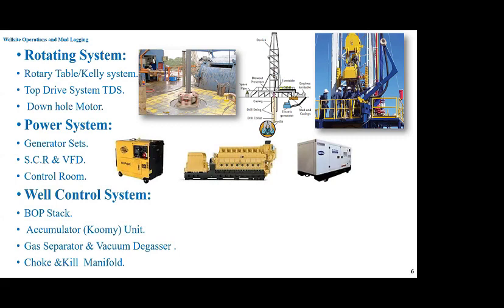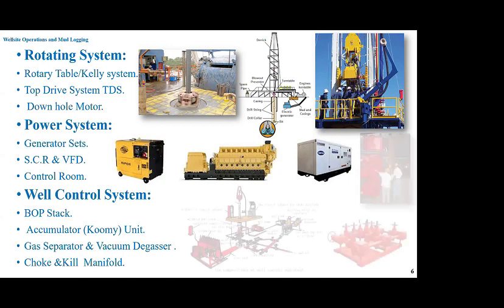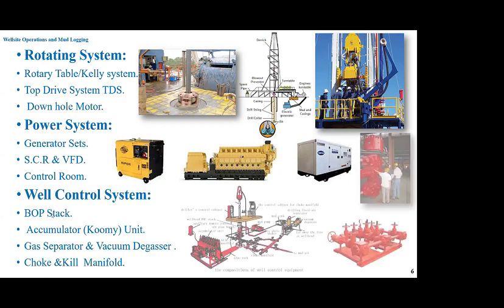The fifth system is the well control system. Starting from the BOP stack, blowout preventer stack, to prevent blowout, and the accumulator unit, also known as the koomey unit, then the gas separator or poor boy, and vacuum degasser, choke and kill manifolds. Also, we will go into details about the well control system and the most important parts of it, inshallah, in the course.